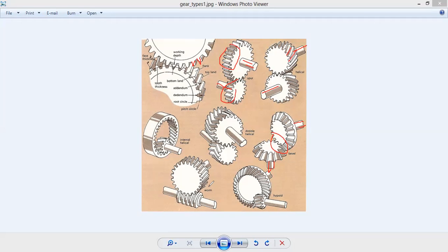And this is a worm gear arrangement. Here we have a worm gear which will have the teeth in a spiral, curvilinear shape, something like this. And onto the other shaft, if it is a parallel shaft, we can have just like the spur gear arrangement, another parallel shaft mounted with a worm gear. Otherwise, if the shafts are not parallel, they are non-coplanar. In that case, we can have a screw rod where the threads on the screw mesh with the gear teeth of the worm gear. So if this gear rotates, then this rod is also going to rotate.